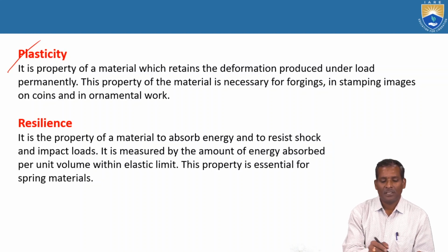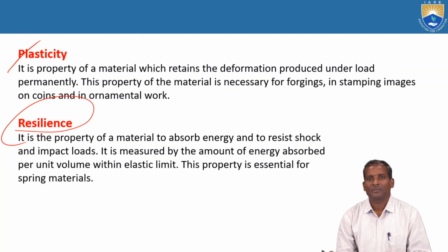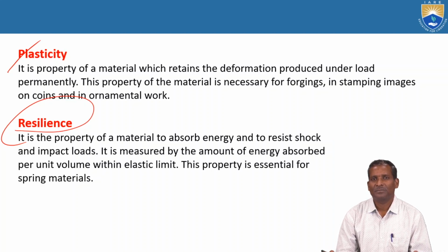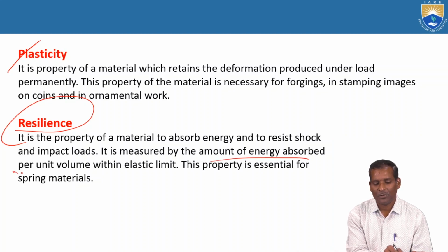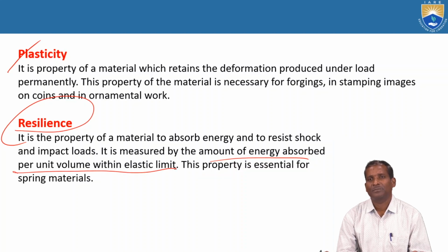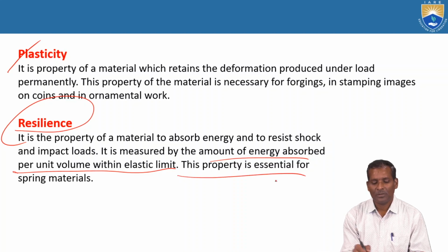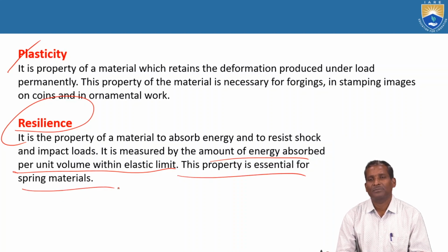Next one is the resilience property. What do you mean by resilience? It is the property of a material to absorb energy whenever the component is subjected to shock loads or impact loads. It is measured by the amount of energy absorbed per unit volume within the elastic limit. This is also important for spring materials.